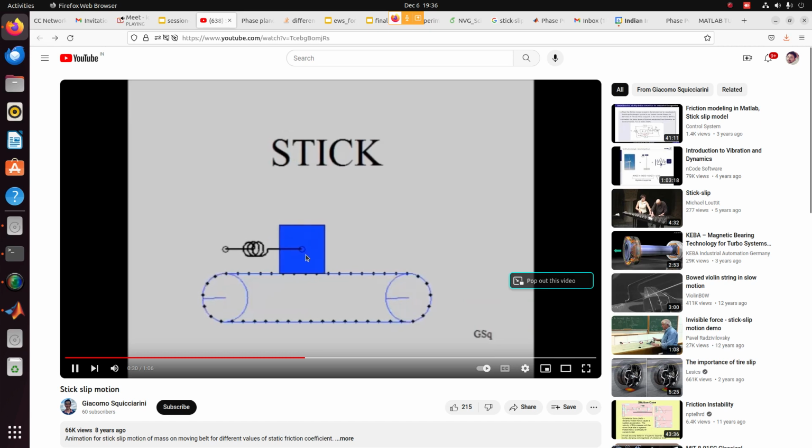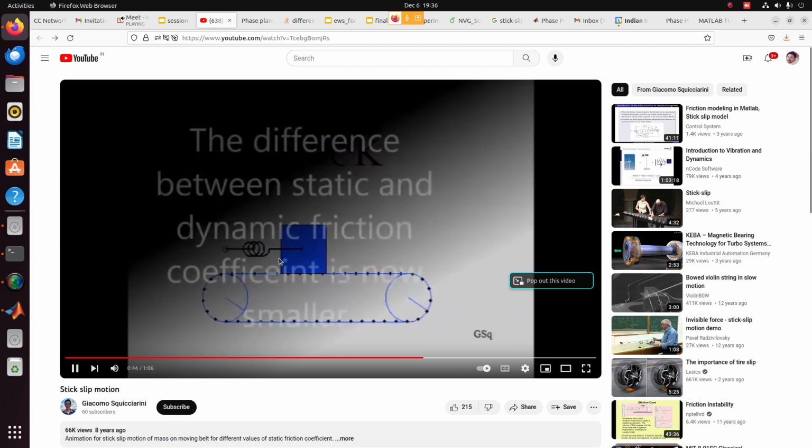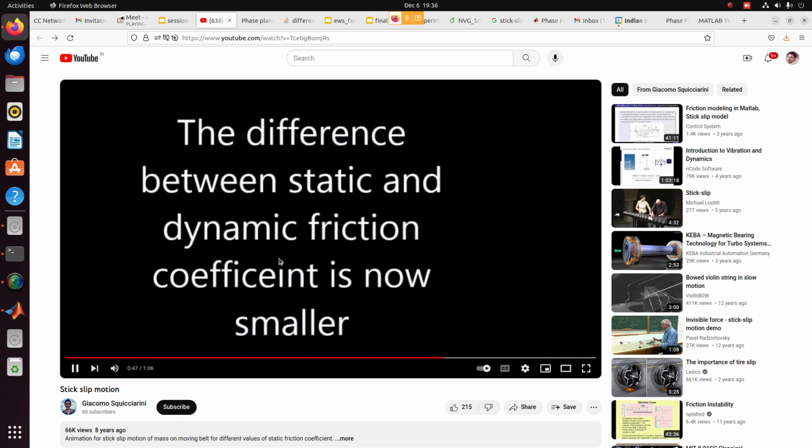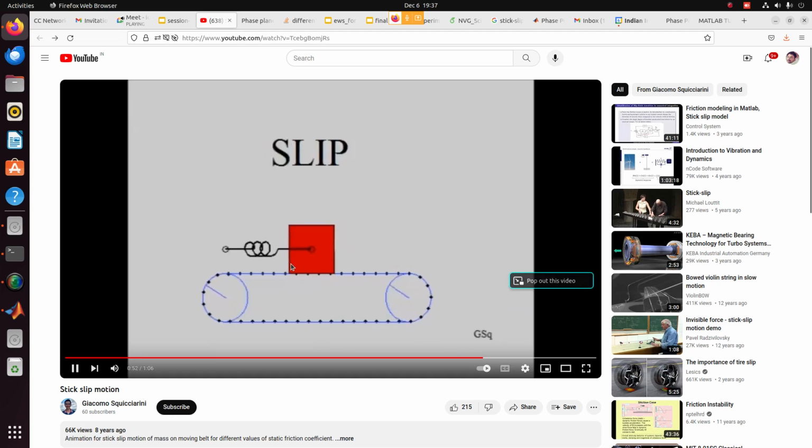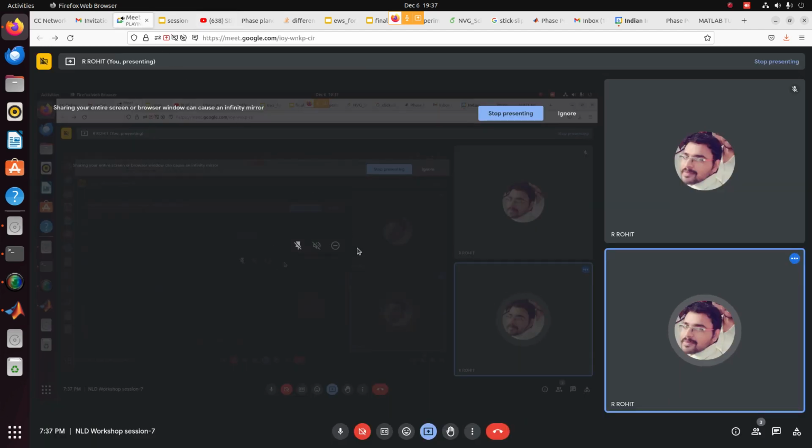Similarly, you can observe that it goes very smoothly in the forward direction, and once it reaches a particular point, it comes back and discharges at a very fast rate. So this is a simple example of stick slip oscillations, and they explain it further with stick slip conditions. This is an example of a relaxation oscillation, where you have a slow build up and a fast discharge.